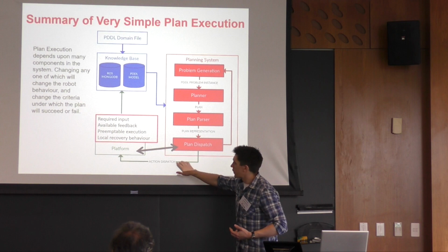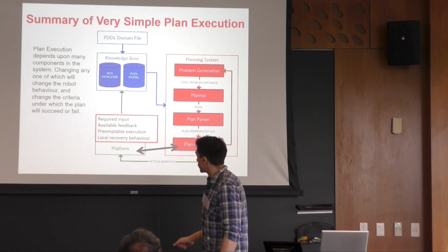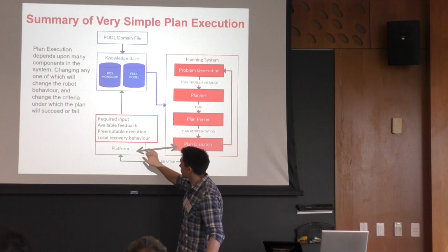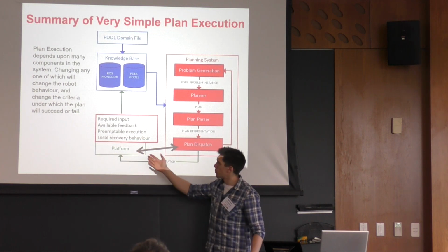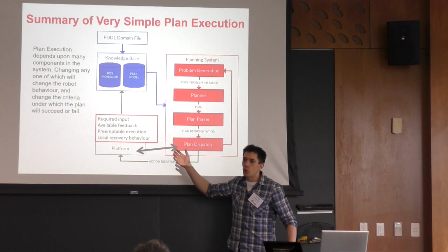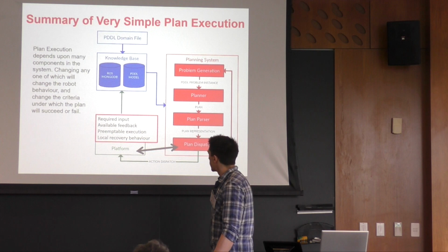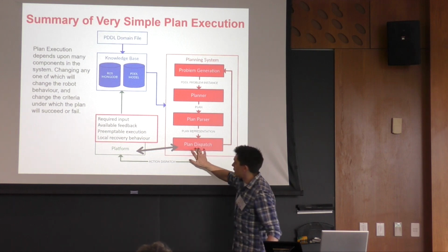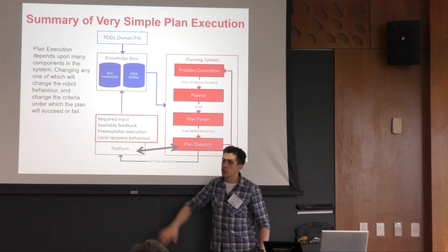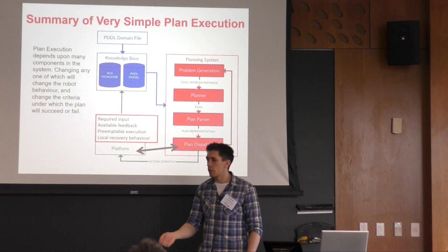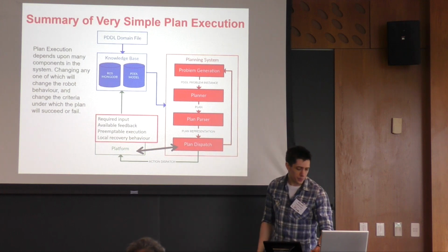You need these interface components to translate your symbolic PDDL actions into the goals for control, and it needs to know which of these actions can be preempted and which ones can't be interrupted safely. It needs to change its implementation depending on whether or not these actions are able to return success or failure, and under what kind of context they can do so.